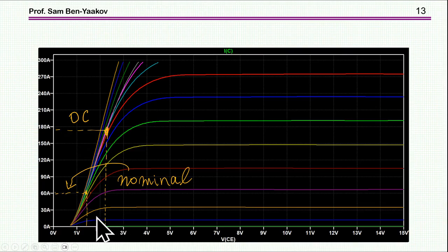So our circuit has to be able to distinguish between two voltages, and when it is below 2.3 volt, then it shouldn't activate the turn off of the gate. Okay, it should turn it off only if the voltage across the transistor is above this value. Of course, you can choose another point. This is just an example. No way it's optimized. It's just for demonstration.